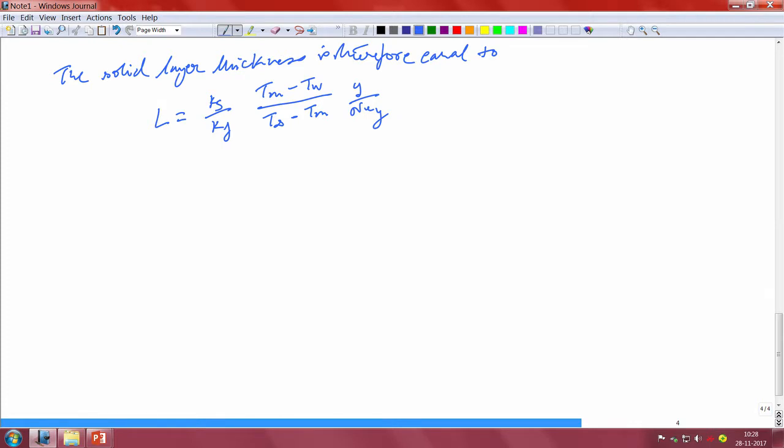From table 4.2, which is from Bejan, and the Prandtl number is 55.9, as given in the conditions, you can see that the Nusselt number is, by linear extrapolation, about 0.487 times Rayleigh number to the power of 1/4.